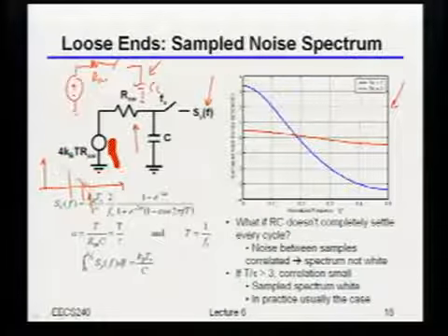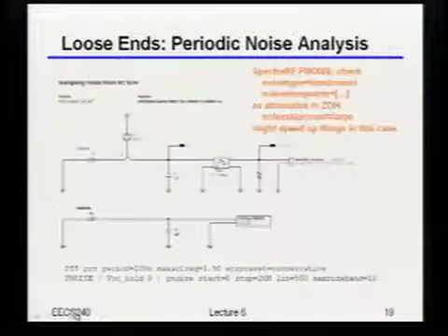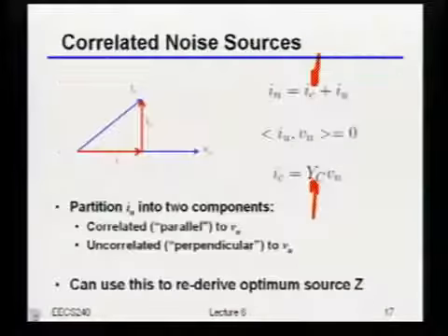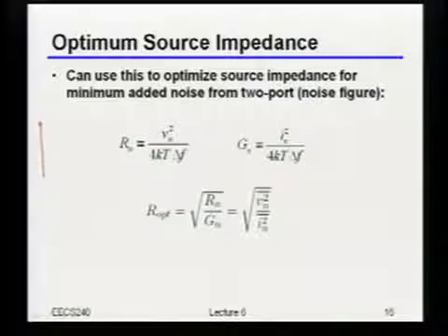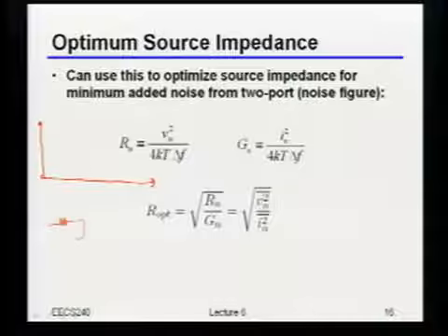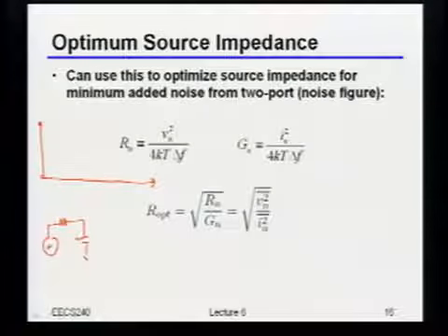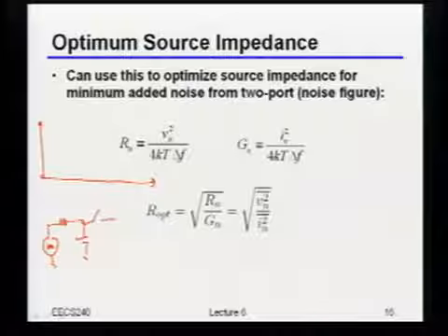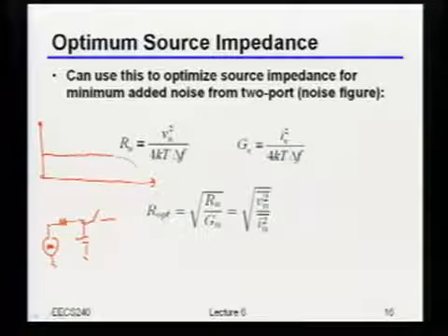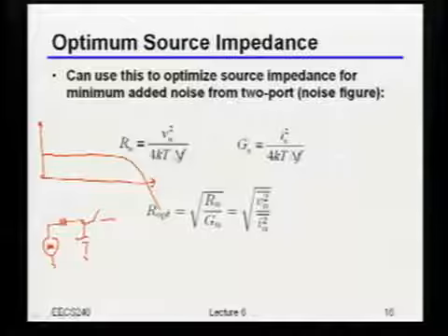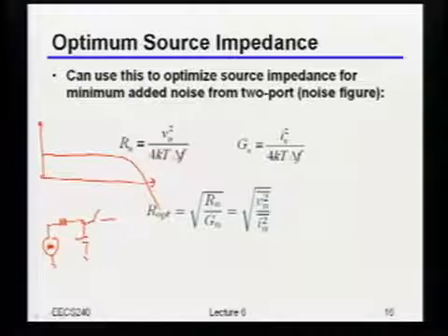So let's find some space to sketch a little bit, and I'll do it over. I've got a little bit of space here, so why don't I just sketch right here? Okay. So if I have that RC circuit, which just looks like this, and I've got, of course, the noise over there, and then I'm just going to sample this thing. I just said that if I had a really fast time constant, then basically I'm not going to be filtering that thing for a long period of time. As an example, let's say that my Nyquist sample rate was sitting right here.